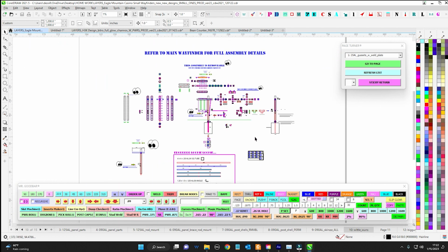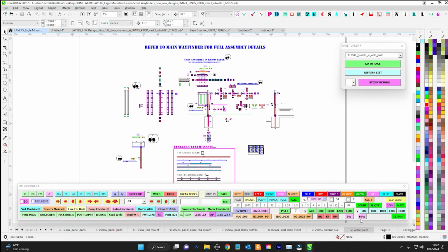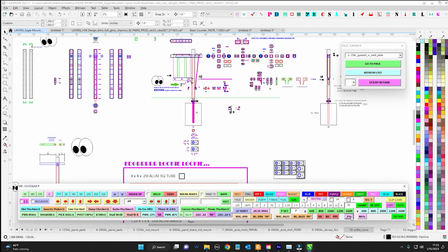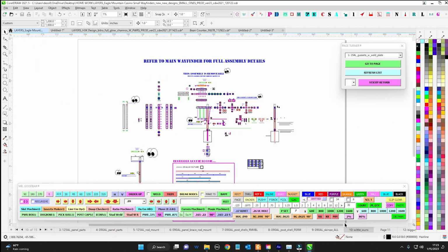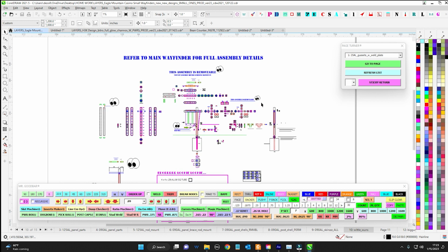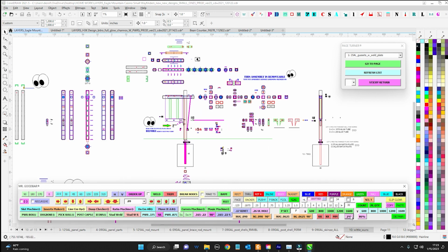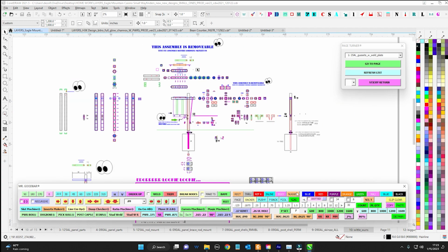But sometimes when I open a brand new file and go to revisit it, it's stuck and I can't zoom in. I found that by forcing it to a different zoom perspective by code, like 2%, it breaks it, and then I can get back to business. So this 2% is just a weird thing I sometimes have to do right when I open a file. It brings it to this zoom, and then I can move around.